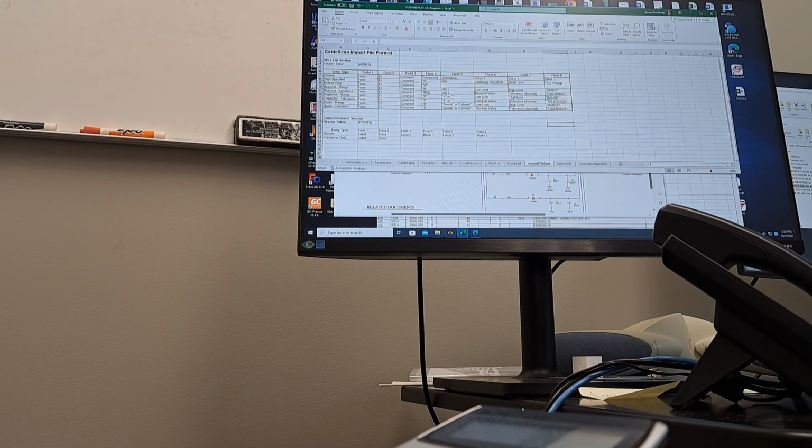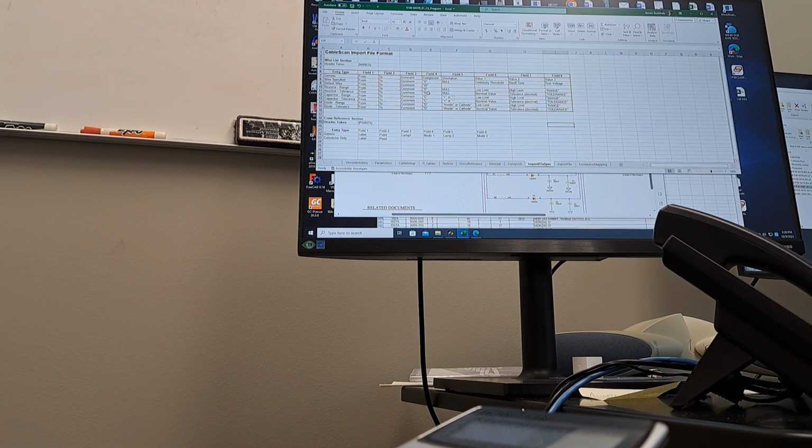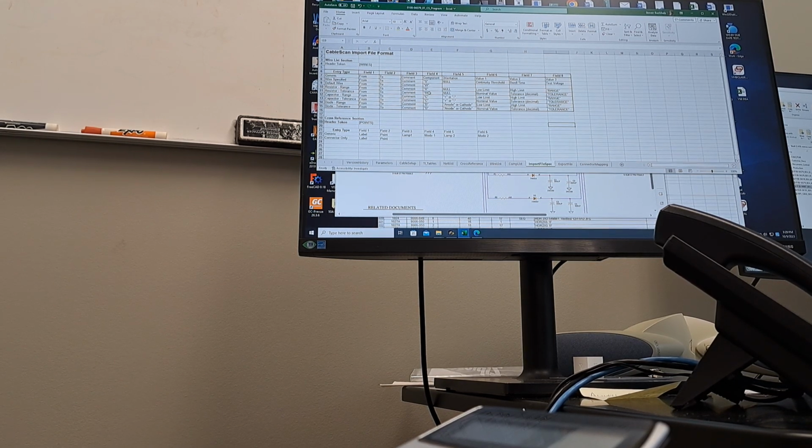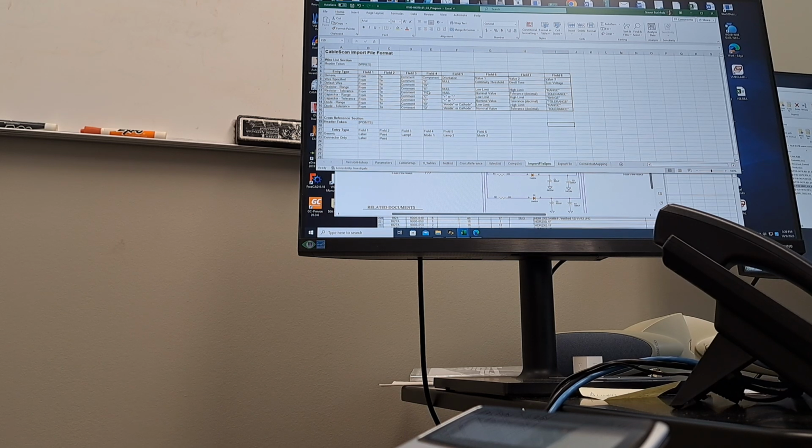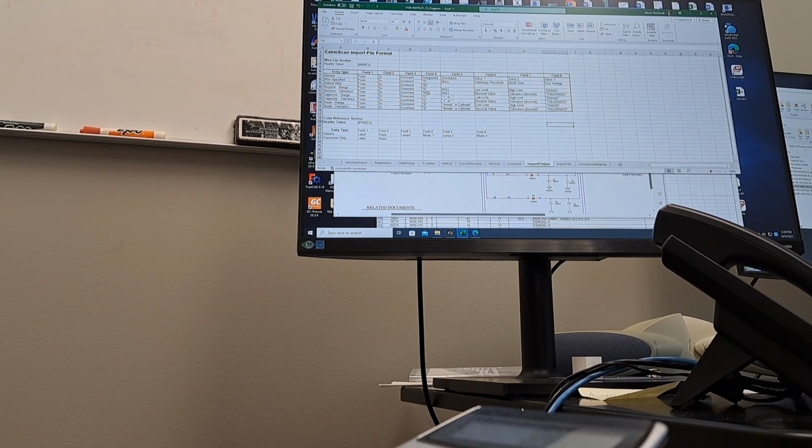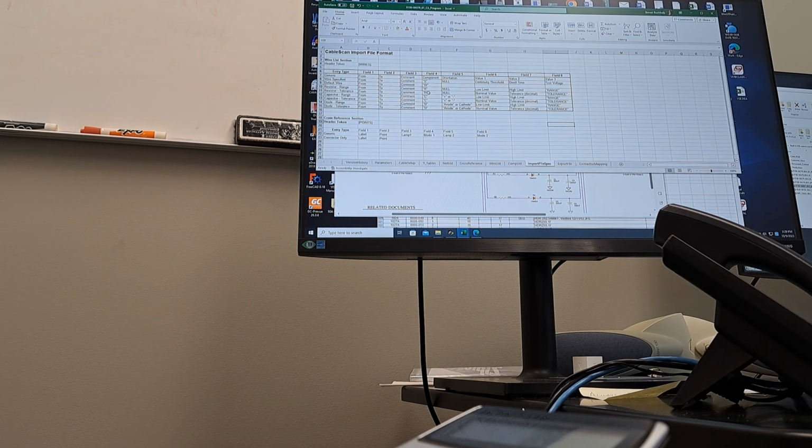And then the manual part of adding in resistors and capacitors is totally up to you to program however you think. You can also use the fact that there's a functional test. That functional test is going to find certain things, so maybe I don't even care about the R's and C's because they'll be caught in functional test. It all is in your brain to figure out what sort of things you want to do.